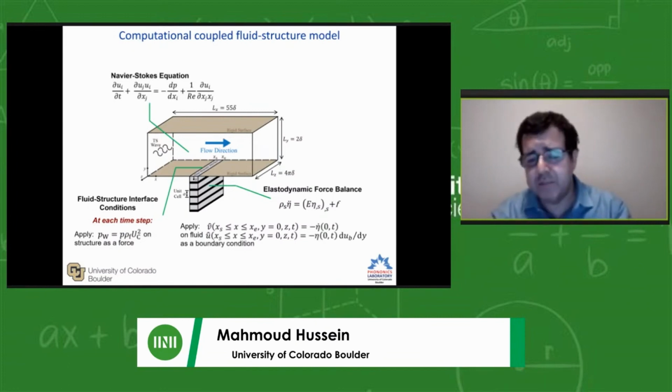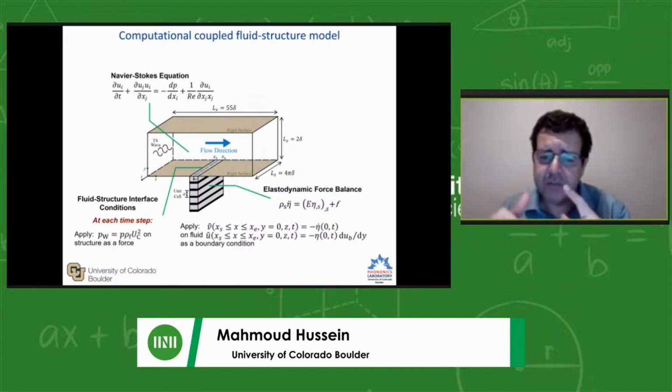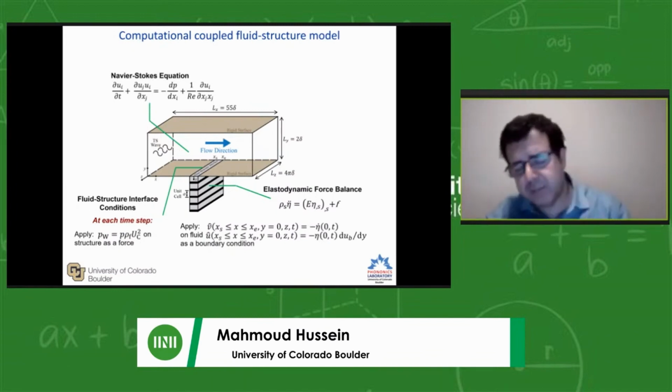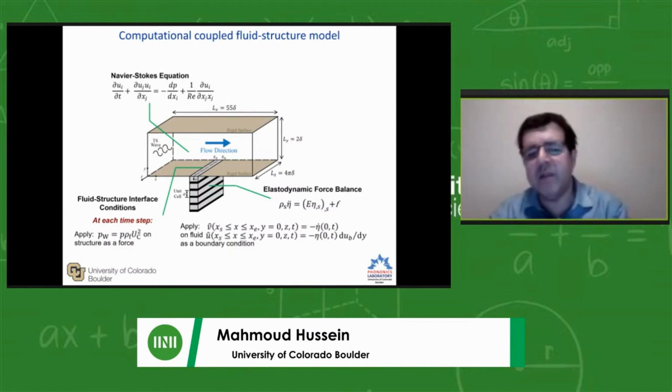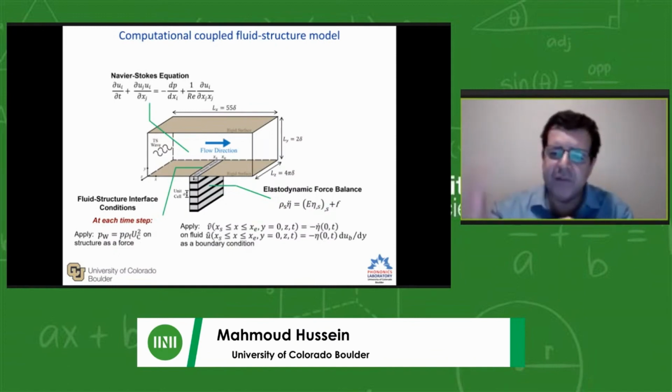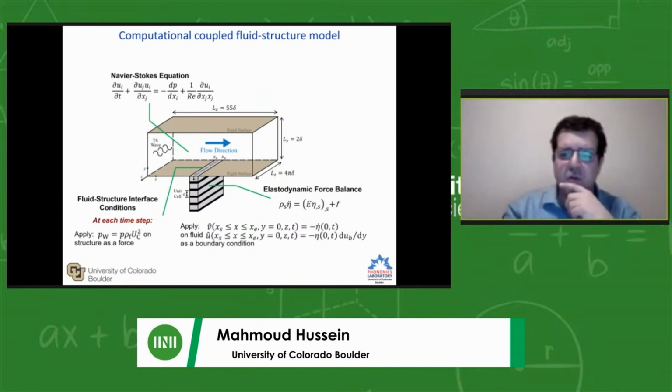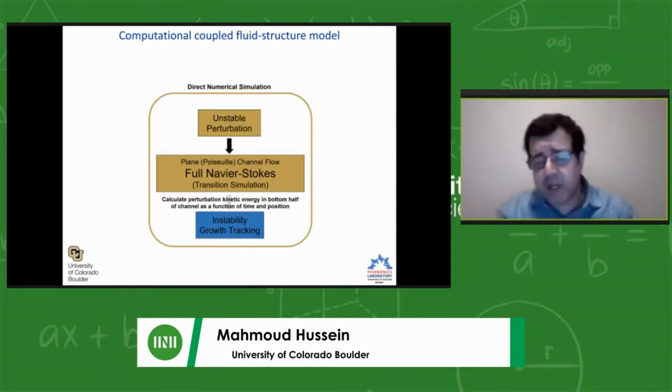The surface essentially remains flat, and infinitesimal vibrations are being transmitted into the flow. So every time step, we evaluate the pressure field on the wall, turn that into a force, apply it to the solid, which generates the elastic wave, and then the finite element code gives us back a velocity that gets applied back to the flow, and then we move on to the next time step and so on. So we run the simulation.